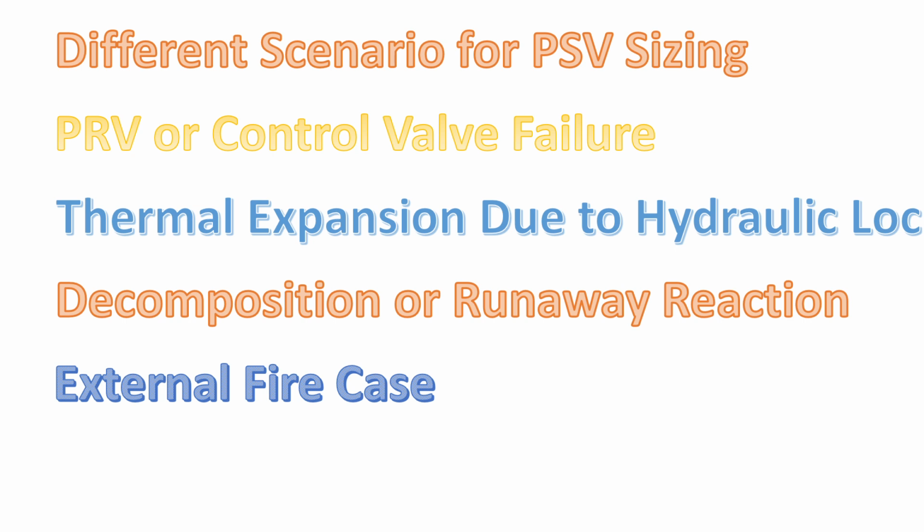Okay, we have a number of equipments or tanks which are filled with organic, inorganic, and solvent-like materials. Those are highly flammable or more volatile, having a low boiling point, which is directly affected by temperature. And in an external fire case, that directly impacts the rise in temperature of the material, which increases the vapor pressure of liquids inside the equipments, that may be a tank or reactor.